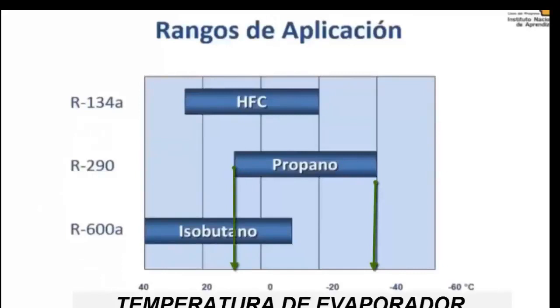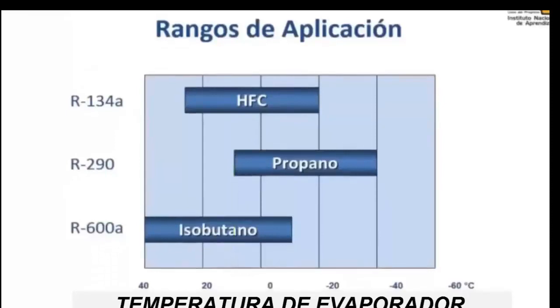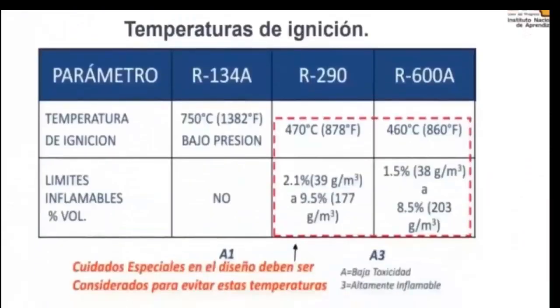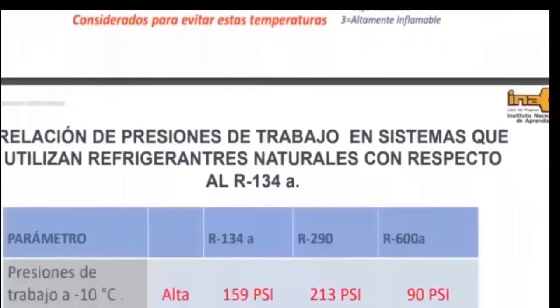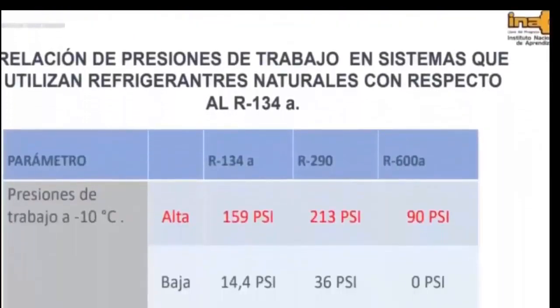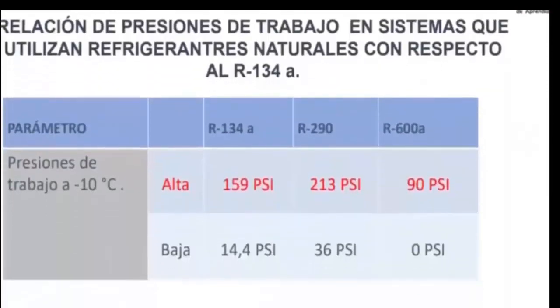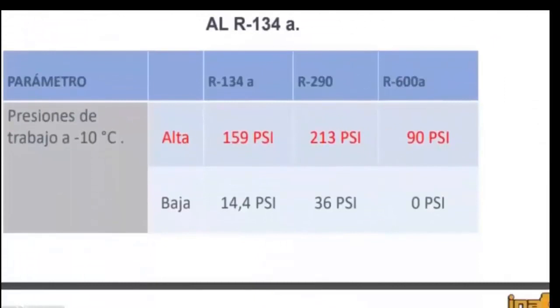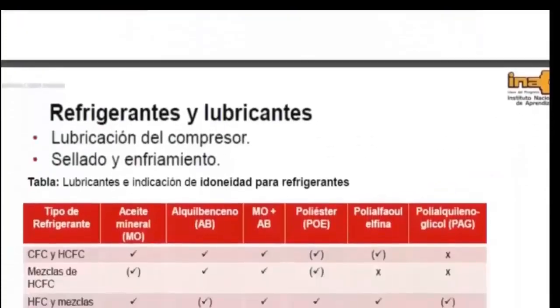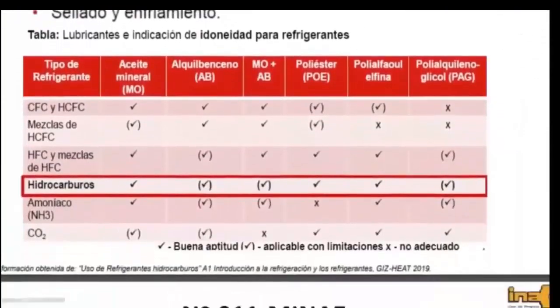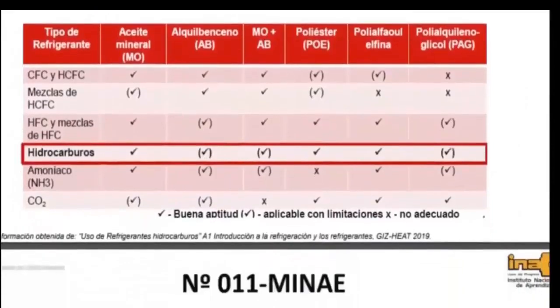11. It has been shown that systems with R290 have lower energy consumption in refrigeration systems compared to conventional refrigerants. 12. Equipment that works with R290 needs less refrigerant charge compared to systems with other gases. 13. Excellent solubility with all kinds of lubricants. 14. It is recommended to use oils with higher viscosity. 15. Due to the density of R290 refrigerant, the charge used can be up to 45% lower than that of R404A refrigerant.